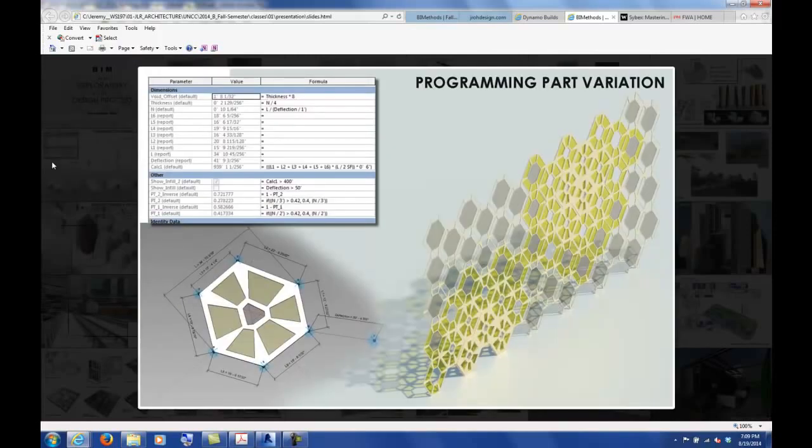We can get a little bit more complex with all of our components, and we can actually make one adaptive component, and we're going to do a lot with adaptive components within this class. Down at the bottom left, this is one component that actually makes, if you look to the right, that particular facade. So that component is programmed with all that data up at the top to change based on some kind of formula that says there's basically this point attractor. You see this point right there. When this point is further away or closer, it dictates whether or not this oculus gets bigger and whether or not the materials change and get thicker or wider or whatever.